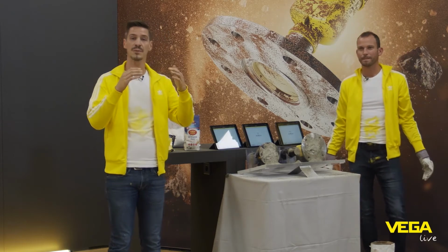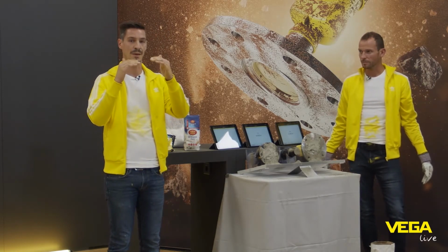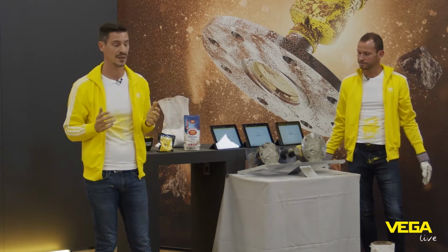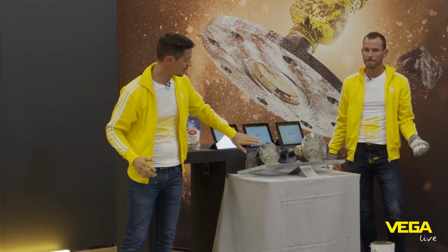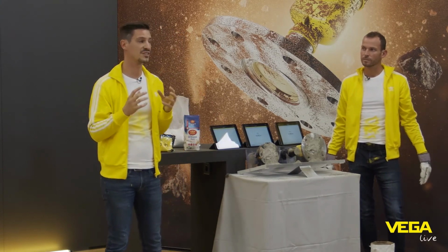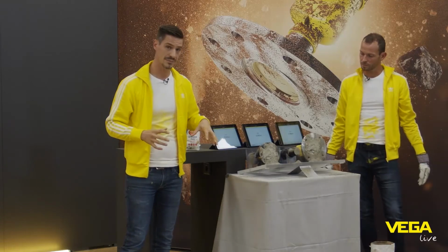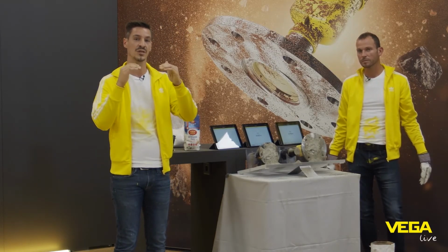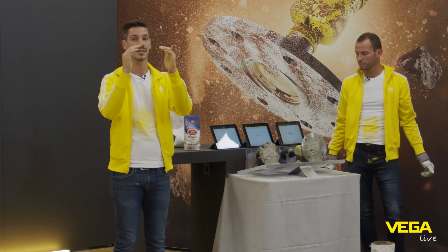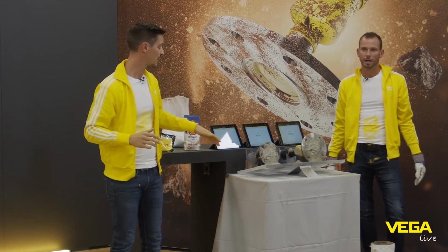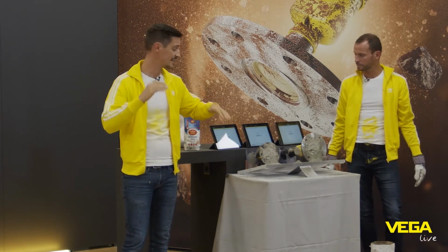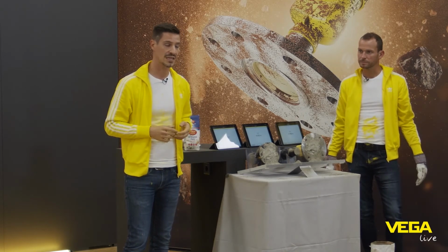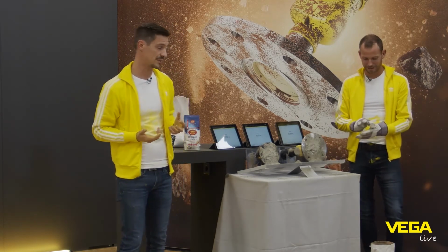The ultrasonic wave is generated in a mechanical way. So a membrane is moving up and down, and generates this sound wave. Now we have above this membrane a very sticky, heavy build-up, and the energy of the sensor is not strong enough to move the membrane and the build-up at the same time. Therefore, the complete energy will be damped away. The ultrasonic device is not able to measure anymore or give a reliable measurement value.